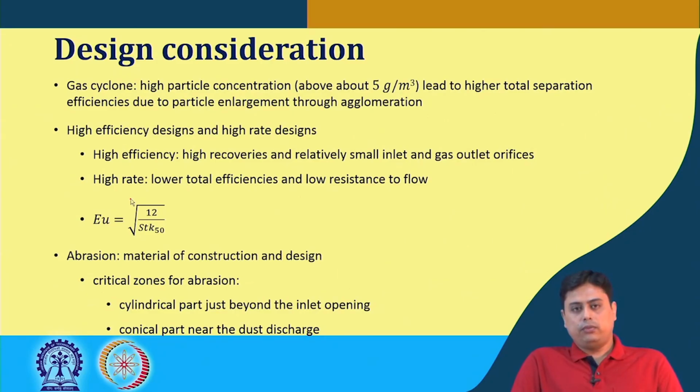If the surface properties of the particles suspended in the gas phase are such that they can quickly agglomerate, then size enlargement can happen. They can stick to one another, and if that happens, the separation becomes easier. So higher total separation efficiency can be achieved in such a case, because if there is high particle concentration in the suspension, the distance between the particles gets closer.